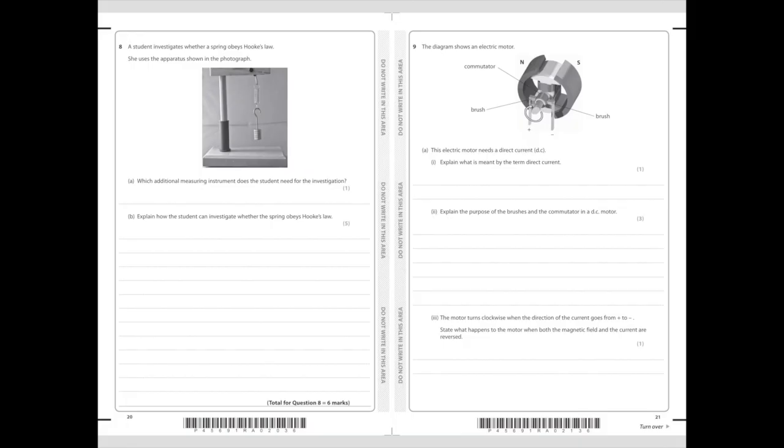And you see on the graph that it should be a proportional relationship, which means that as the weight increases, the length of the spring increases, which makes sense. Then you'll find that the line distorts, and that's because we're no longer increasing proportionally, and that's because the elastic limit of the spring has been reached. It's deformed, it's bent out of shape, and it won't return to its original length. So that's what underpins Hooke's law. Now we're going to look at a past exam question on it.